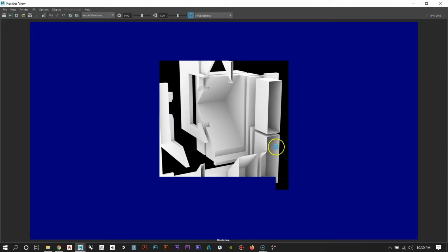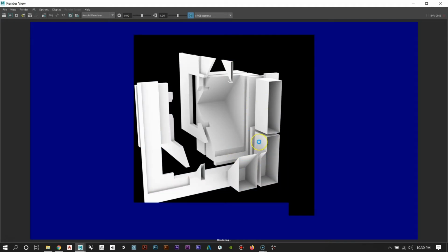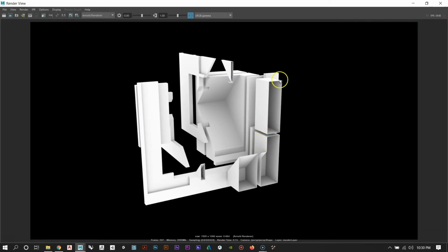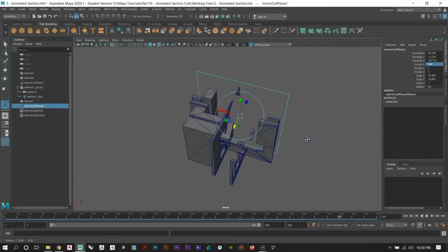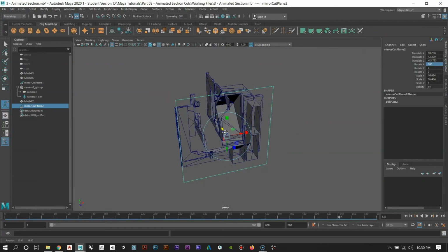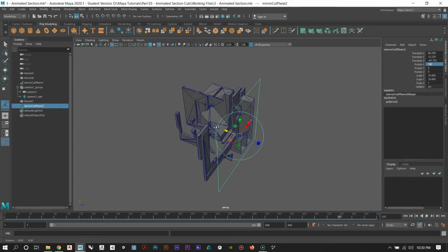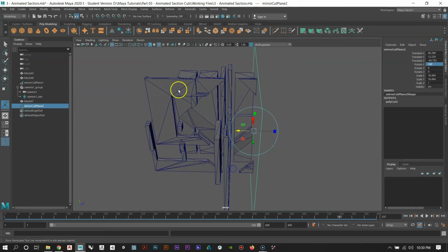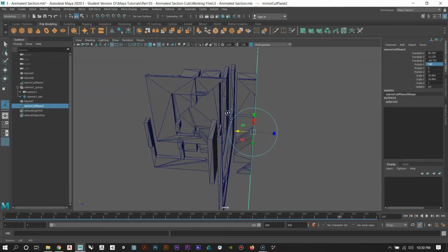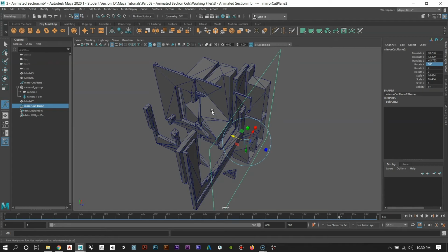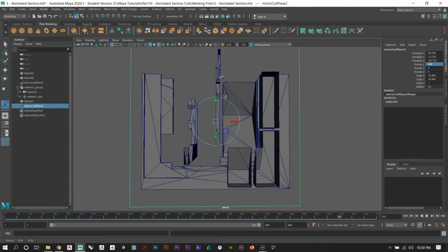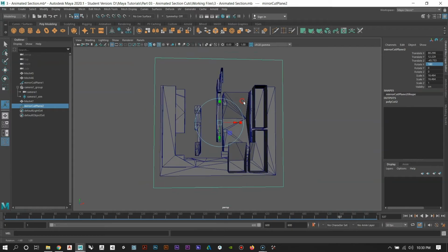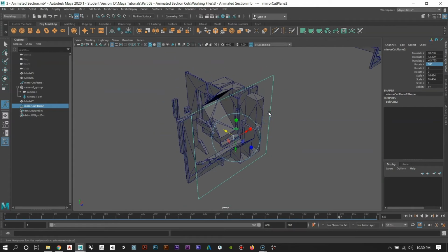Okay. So if you don't want that and you want it to look as though this isn't hollow but it has like a poche or thickness to it, what you can do is create what's called a custom material. So we're going to hop into that. Basically, all it's going to be is an occlusion material applied to the outside, your standard black and white kind of shaded color. And then on the inside, we're going to apply a jet black material, and it'll give the illusion that you're cutting through a solid object.